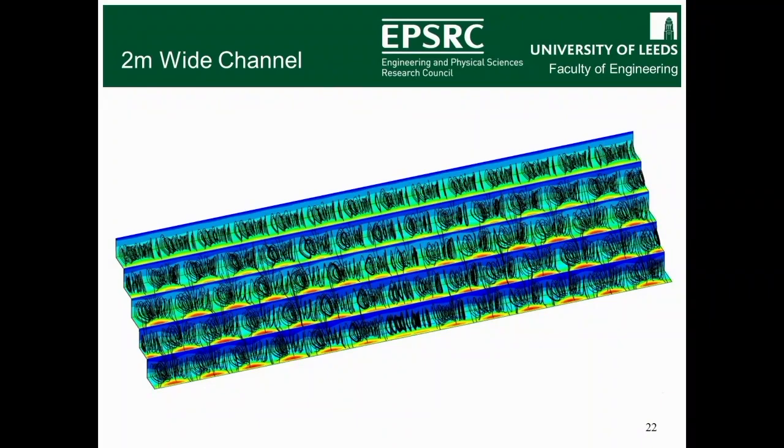But yeah, so to conclude, I've used different combinations of multi-phase and turbulence models to try and predict pressures, velocities, air volume fractions, and free surface depths in step spillways. I've been able to predict the velocities, the air volume fractions, and the free surface depths well in the aerated region, using the Eulerian multi-phase model in combination with the SST k-omega model. And also in this other spillway, we've got this unusual pattern of vortices that seems to repeat itself as we increase the width of the channel.